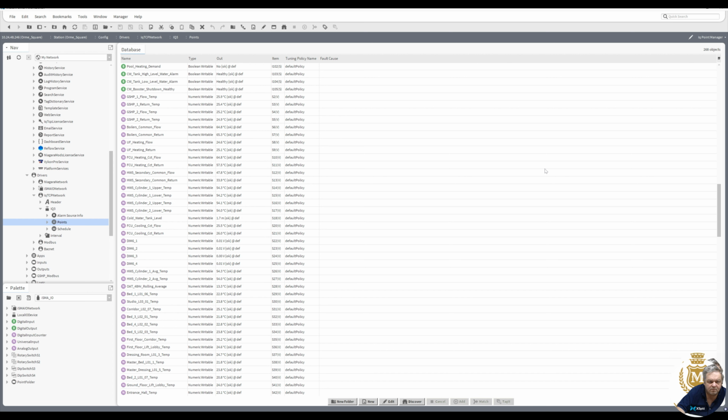Let's scroll down. These are now the sensors. Ground source heat pump 1 flow sensor, boiler flow and return sensors. So all temperature sensors. These are these DIM 6s. These are the 6-channel digital inputs to analog output. DIM 1, 2, 3, 4, and there's some more further down.